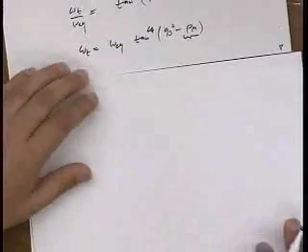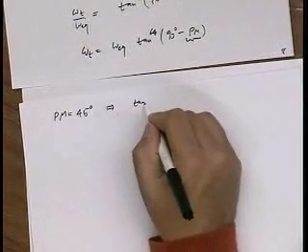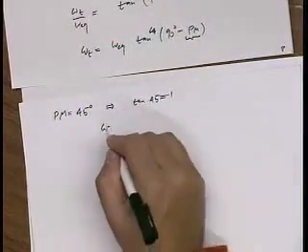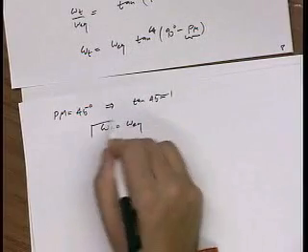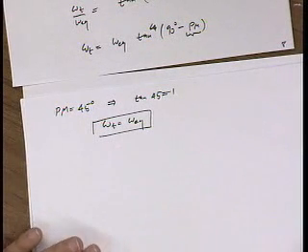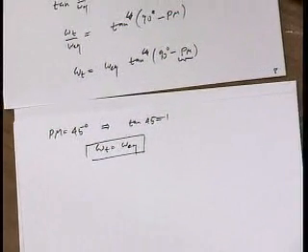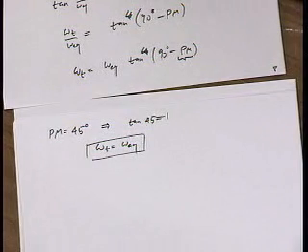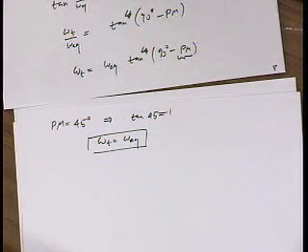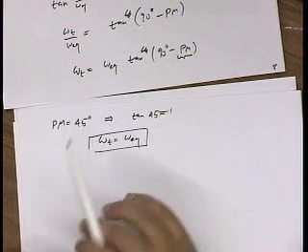So, of course, a very simple case occurs when I have 45 degrees phase margin, because tangent of 45 is just 1, and that corresponds to choosing unity gain frequency equal to the frequency of your equivalent non-dominant pole, right? Usually, though, 45 degrees of phase margin is too aggressive. You're going to get quite a bit of ringing. If you look over process and temperature, it could be too much. So most designers will not use 45 degrees phase margin.